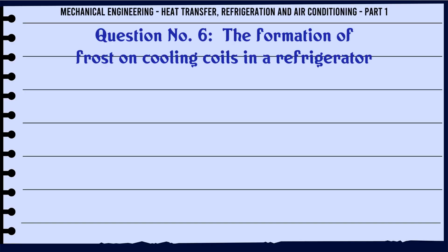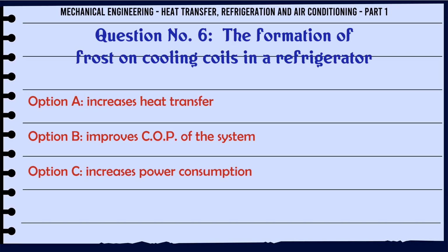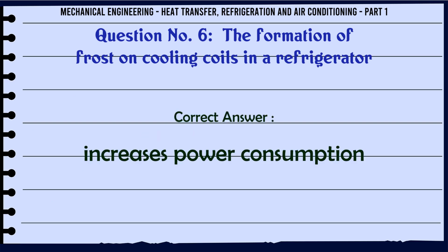The formation of frost on cooling coils in a refrigerator. A. Increases heat transfer. B. Improves COP of the system. C. Increases power consumption. D. Reduces power consumption. The correct answer is increases power consumption.